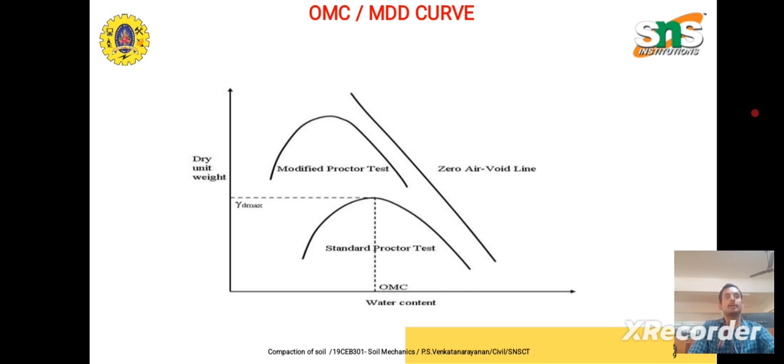To sum it all up, compaction increases dry density by removing air content. It is essential for a strong, stable and safe foundation. Proctor tests help us to find OMC and MDD, which represent various compaction characteristics of soil. And proper field methods make sure that compaction is achieved to a great extent, and the soil is more suitable for construction of heavier structures such as roads, embankments, airfield pavements, etc.